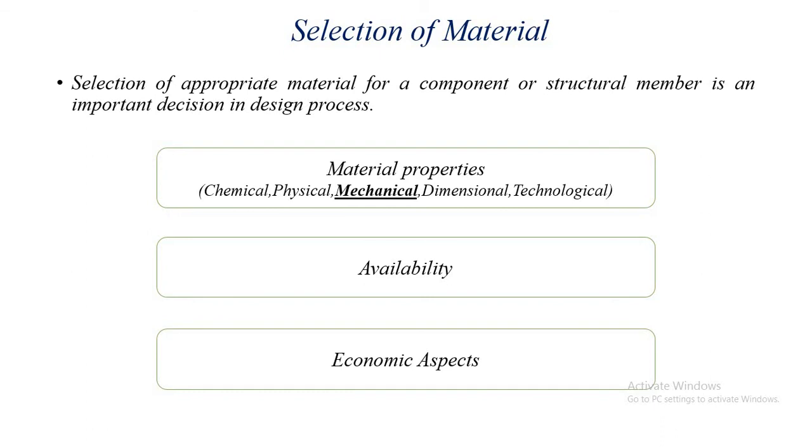As a mechanical design engineer, it is important that you ask the following questions before the procurement of the raw material. First, is the material available in hand? If the answer is no, can we get it in 1 to 2 weeks? If the answer is yes, how much quantity of the raw material is required? Second, what is the nature of suppliers and how many suppliers are available? Third, is there any special method required for fabrication of the raw material? If the answer is yes, then the designer needs to establish timeline for procurement.